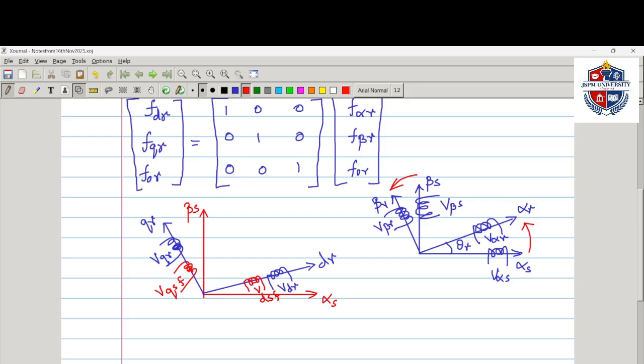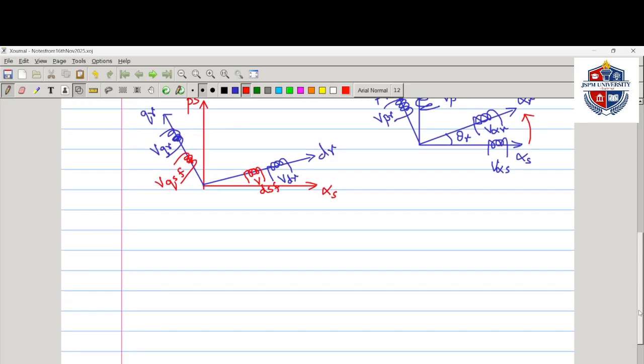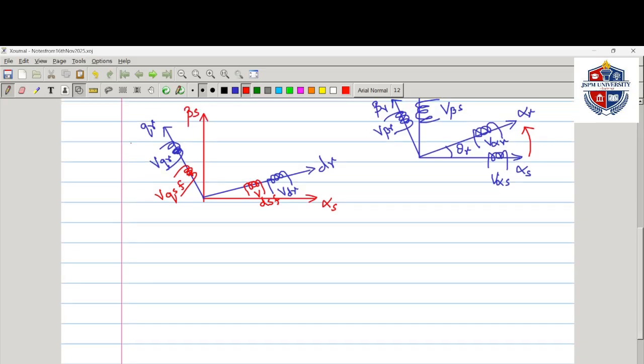So I hope you understand. Now the rotor variables are as such the same. Even I can use the same blue color. At the same time, the stator variables are moved to the rotor. Therefore, in this reference frame, the stator variables are fictitious. So accordingly, this angle we have already noted as theta. We have added this angle as theta.